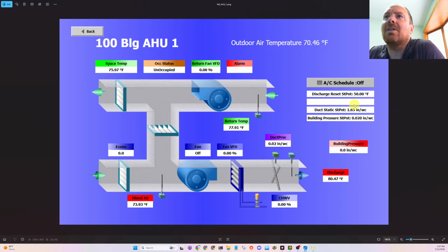Well, I guess the systems are off. But this should be an average space temperature sensing. So the air handling unit would have supervisory level logic, averaging the space temp sensors. Hopefully it's an optimized average.